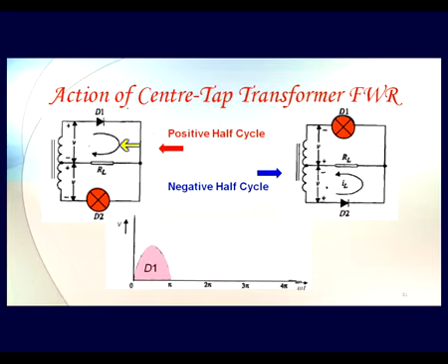Now if you compare these two circuits, the direction of current in both the half cycles with respect to RL is the same. In both cases, the current is flowing from right to left. So at the output, even in the negative half cycle, at the load we see the output flowing in the same direction. This is how we are successful in reverting the polarity by using two diodes in full wave, and so by alternating positive and negative we are getting output which is now positive, positive, positive and positive, and this goes on like this.